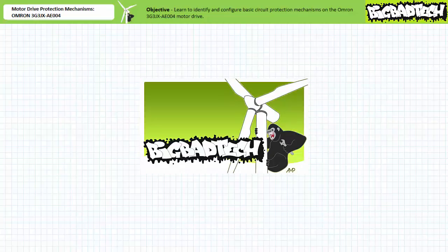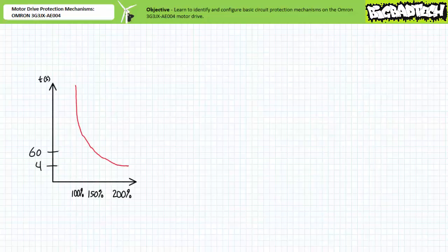If you recall from the overload relays lecture, available at the Big Bad Tech channel, a Class 10 electromechanical overload relay will trip in 10 seconds if current is 6 times the rated value, with a curve describing the behavior of the overload at different current magnitudes. A motor drive can mimic the behavior of an electromechanical overload relay by continually monitoring both current magnitude and time. If a period of sustained high current draw is detected, an overload trip can be signaled.